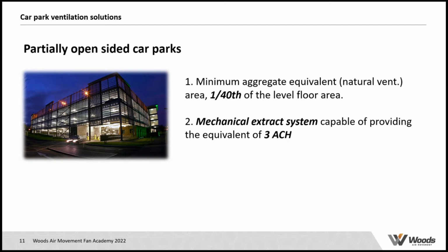That is recognized in the building regulations, where it says that if you have a car park that does have openings to the outside, not meeting the 1/20th of the floor area, for instance meeting the 1/40th of the floor area, then you will require mechanical ventilation, but not to the extent of a fully enclosed car park, which we will touch on in a minute.